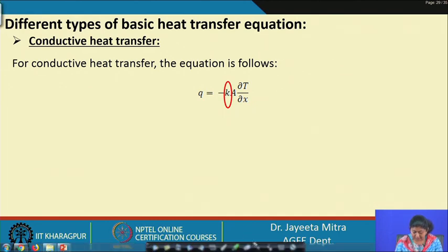We can think of it this way: if this is a solid wall having dx thickness and the heat is flowing from the higher side to the lower side, where T1 is greater than T2. Since heat is flowing from the higher to the lower side in the direction of positive x, that is why we are putting a minus here. So, Q equal to minus K A dT by dx.